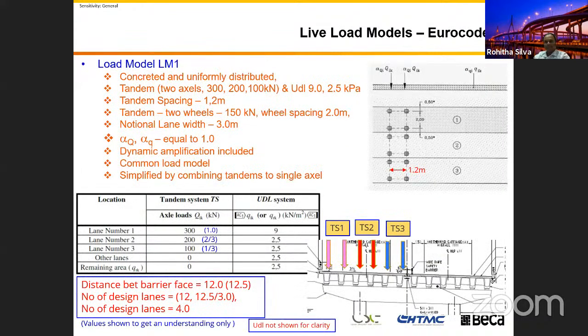This is not theory. This is real because I have designed enough bridges to tell you this. And I don't want to design using Eurocode to explain it to you then. Again, to design your bridge for your traffic, that is Eurocode load model LM1.